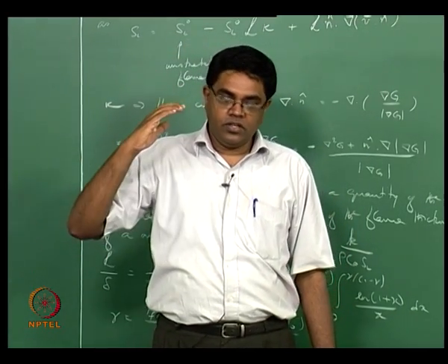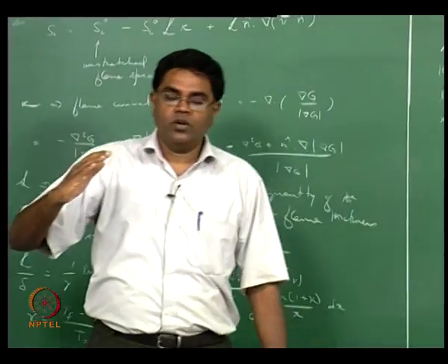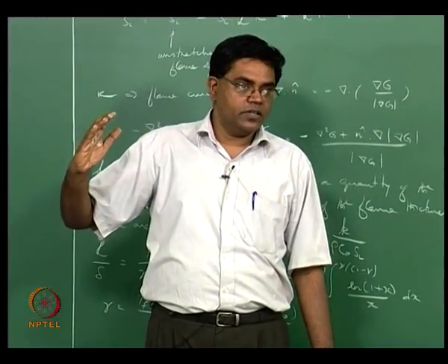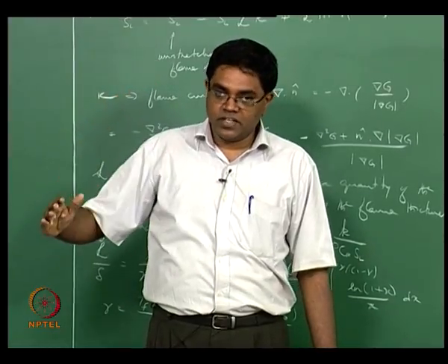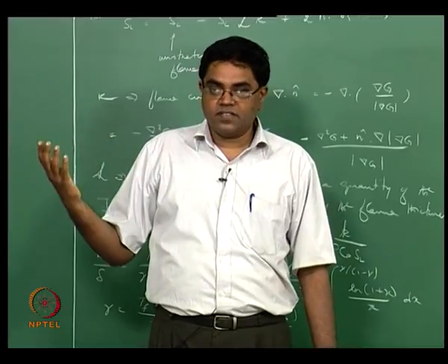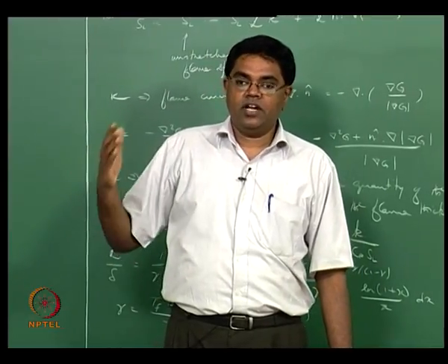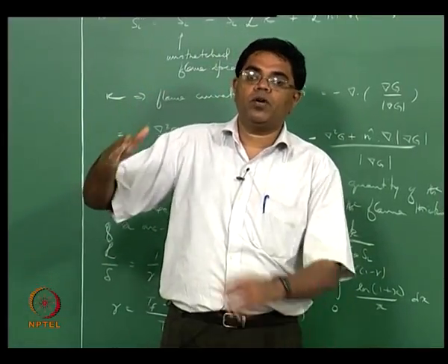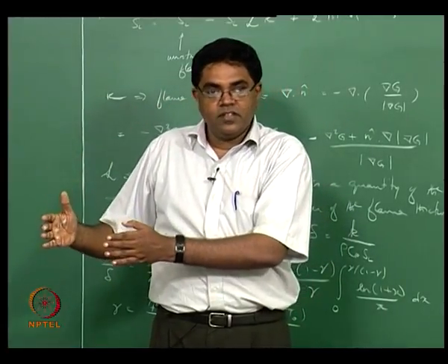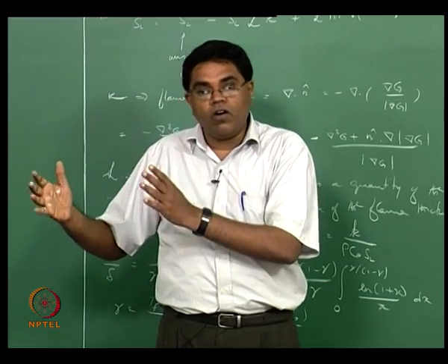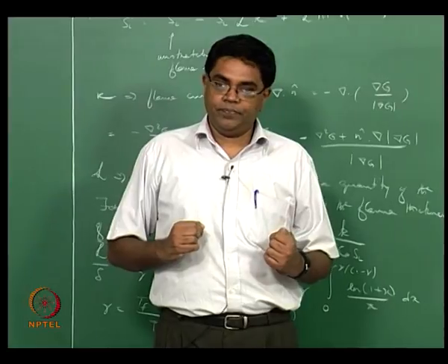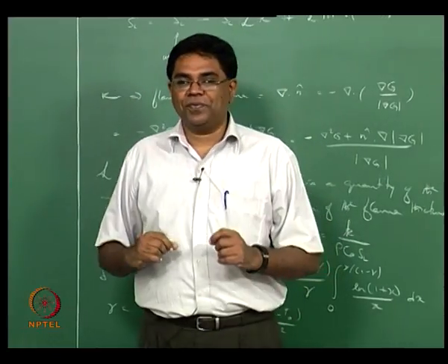Of course, within the framework of the G equation, we don't bring into effect the thickness of the flame. So it's as if the flame has a thickness, and we are saying that S_L is a constant, it doesn't change, and therefore we don't have to worry about a varying thickness of the flame near the base, or a varying flame speed as we approach the base. But none of these things is true.